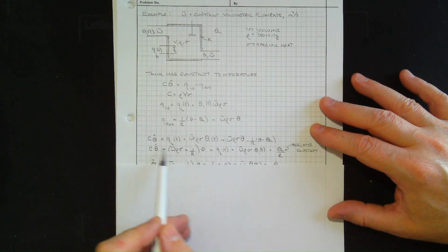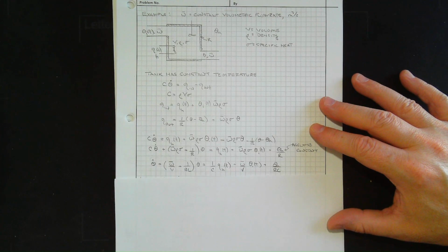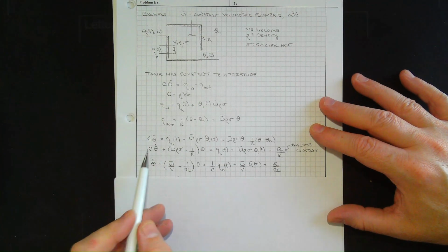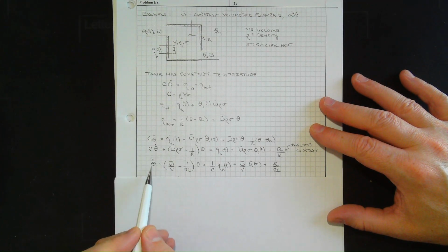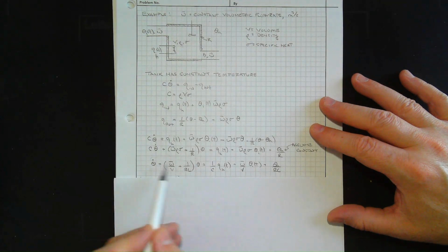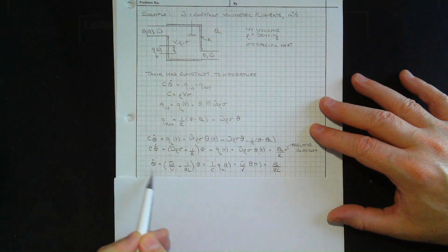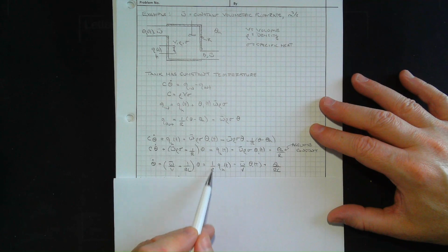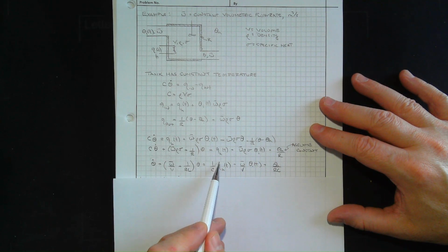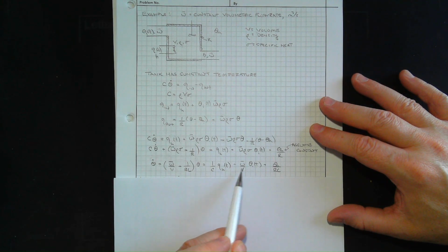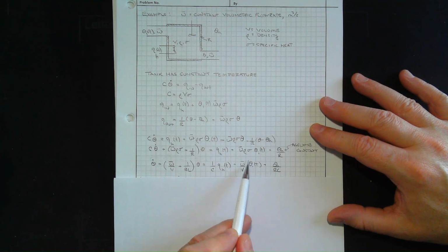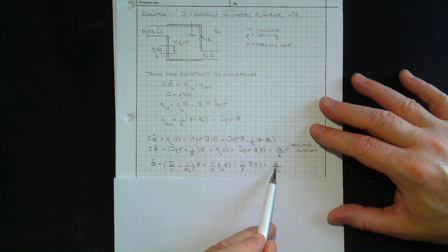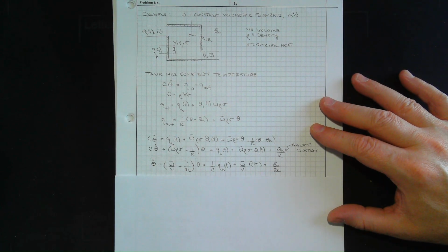So here we're gathering these things, and now I'll divide through by that C. And so here I've got the temperature in the tank. So here's the differential equation: it equals 1 on C, the heat supplied, W on V, or omega on V, fluid input temperature, and then we have the resistive loss to the atmosphere.